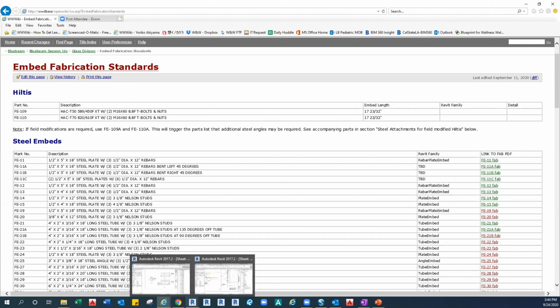You could duplicate the type, and then rename the data. It's kind of an involved process though. Right. But I'm not sure. That's why I said to James I would like to double check with Emily. That's her intent. So the family doesn't have to change. Just copy that family and call it a 109A, and copy the 110 and call it a 110A, because they don't need to be different.